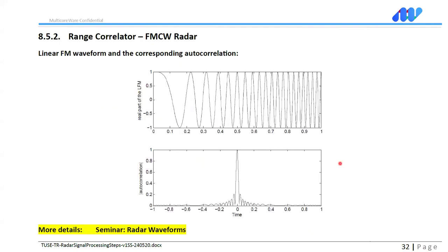And for FMCW signals, you really have very high gains right at the range correlator. You can get even larger values. So again, when you analyze match filters and convolution operation for radar waveforms, it's interesting to see that all generate peak values successfully right at the center of each target. So if you have 3 targets, you see 3 peaks. So no matter what type of waveform you use, you see those peaks.